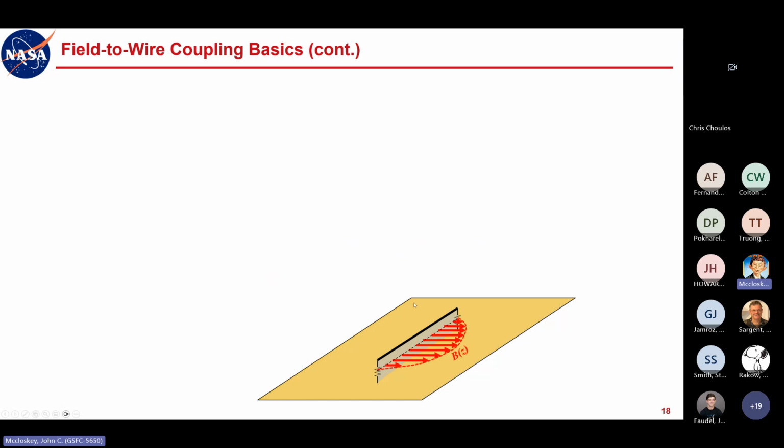All right. So now, just looking at this more intuitively, sparing you the math to some degree, if we increase our frequency to the point where, like what's shown in the diagram here, the length is exactly 1/2 of a wavelength, we'll look at this snapshot in time where the B field has this distribution over the length of the cable. You're getting exactly half of a cycle over the length of the cable. This will give you your maximum flux.